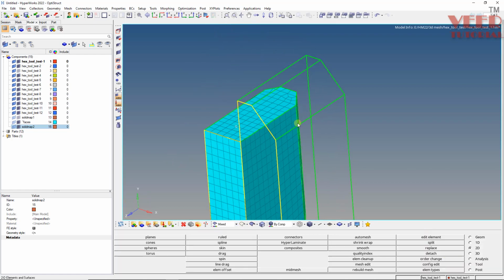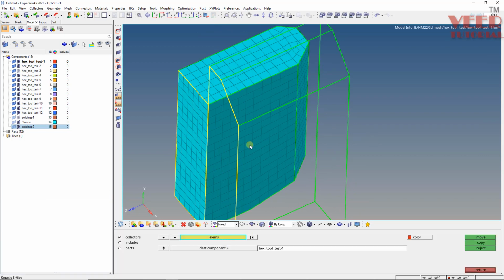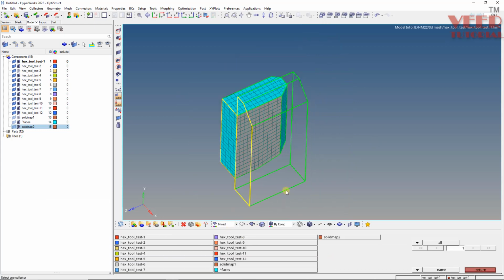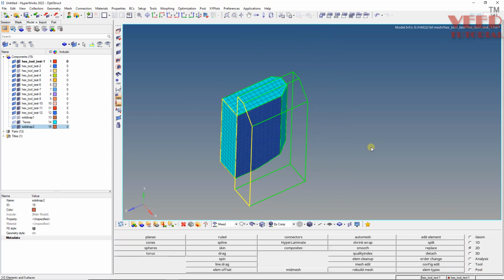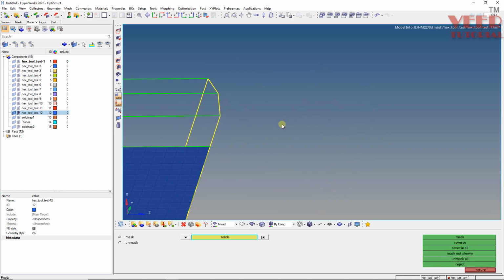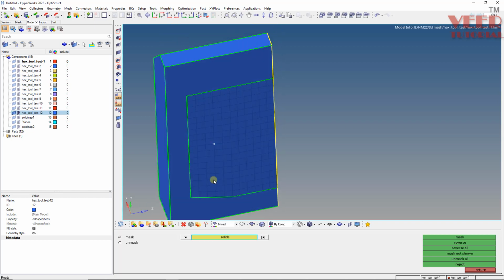Return here. From here press shift plus F11 and select this face of the element by face, and in the destination select this other part. This is move. Return. Now I can go to, so this is basically our hex 12. Make a right click and isolate only. Okay, so you don't need the right one part, so hide this, then solid it. So here you can see basically we have taken the projection of the meshing we have done earlier.